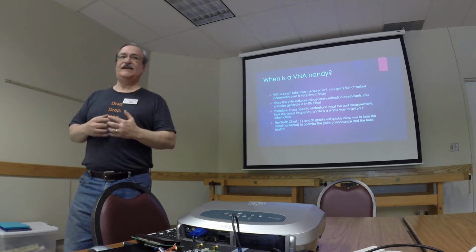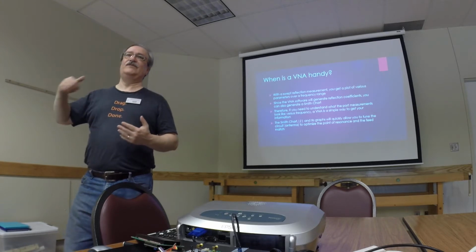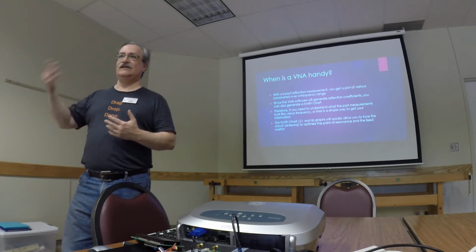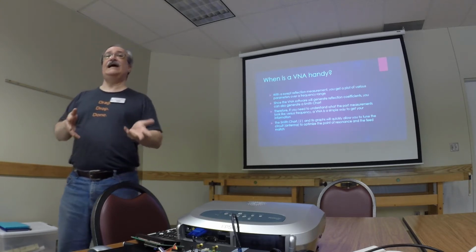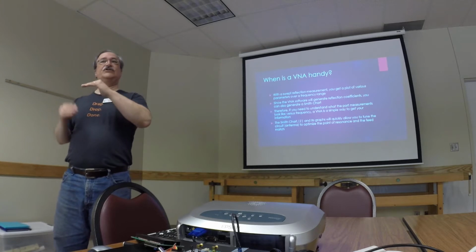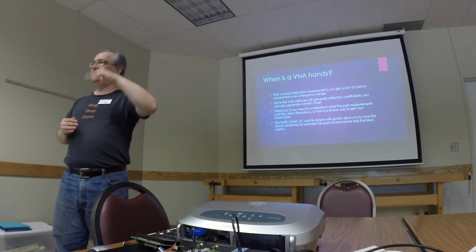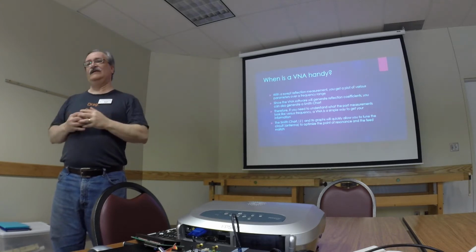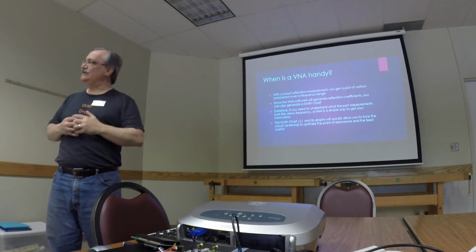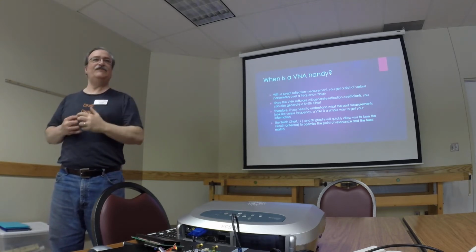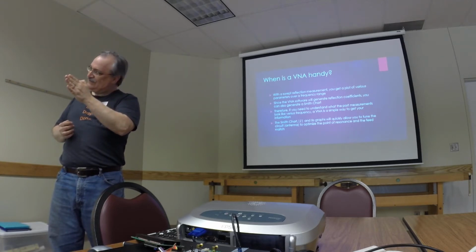He did a lot with NASA to be able to pick up the telemetry from the moon, from the LEM and all of that. So he knows his stuff, and he had in there a chart that showed feed impedance versus distance off the ground in fractions of a wavelength. So I figured it out real quick: what fraction of a wavelength at 22 feet I was at. And sure enough, 100 ohms.